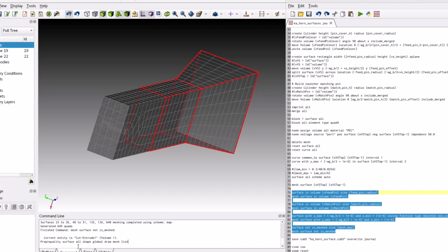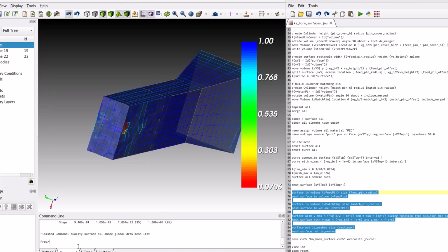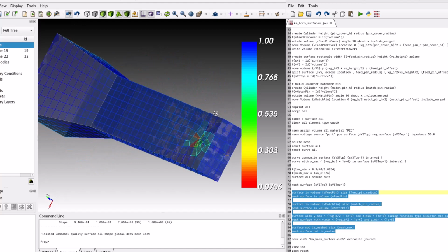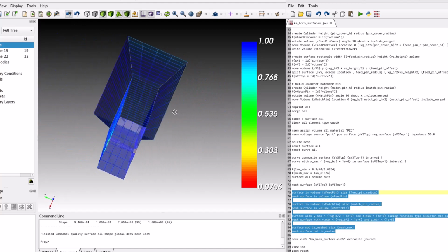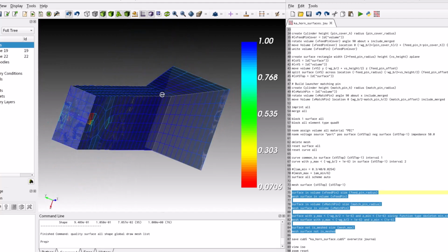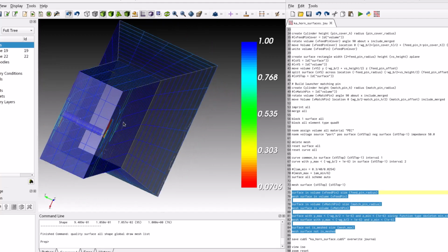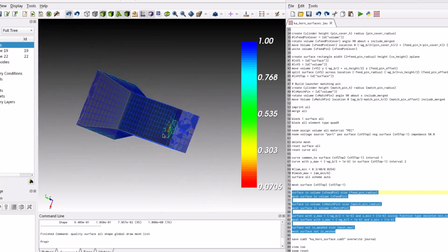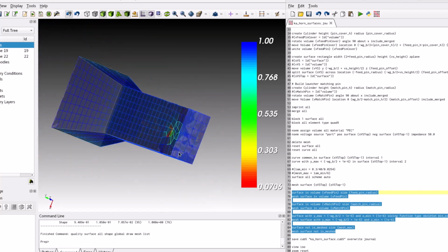We can save this surface mesh as a cub5 file, the native file format of Nullspace Prep. Saving meshes as cub5 files ensures a lossless representation of the original mesh data. For further reference, visit the docs folder of your Nullspace EM installation to follow along with more examples and understanding the different ways to manipulate and mesh objects using Nullspace Prep.